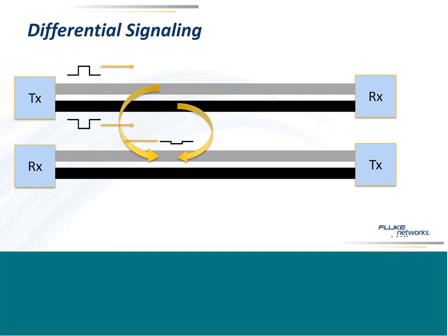But not entirely, because if you look at my picture here, you'll see that the black wire is a little closer to the gray wire below it, and so it picks up a little bit stronger signal from the black wire, the bottom cable, than it would from the gray wire. And that means you're still going to get some crosstalk there. Even though it's been greatly reduced, there's still some. So how do we get rid of that?